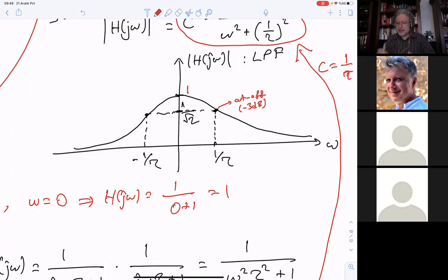The Bode plot is flat, and then it reduces, and that is the cutoff frequency. But the Bode plot is just a straight line approximation in decibel scale, as opposed to this H of j omega plot. This one is the real and actual magnitude frequency response. So it's better than the Bode plot. It's more accurate, but the Bode plot is just an approximation. You say that there is a cutoff or minus 3 decibels point, you draw it straight up until there, and then you draw a straight line going downwards. That was the Bode plot that you learned.